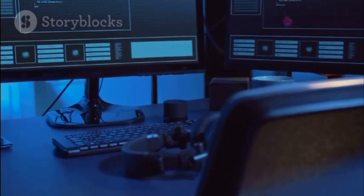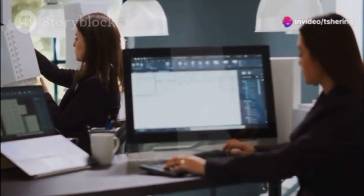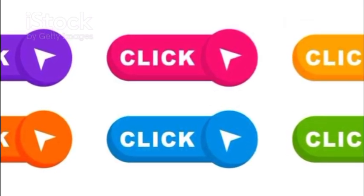Next, we've got the Grid. The grid is like a visual guide that helps you align your objects. You can adjust the grid spacing to suit your needs. To turn on the grid, click the grid button on the status bar or press F7.